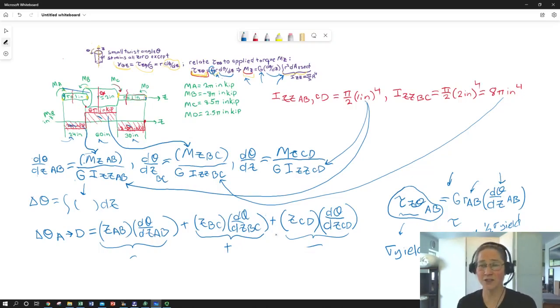I use the shear modulus to calculate all of my properties for a given applied torque or a given required twist rate or total twist angle, whatever, and the part dimensions. And then having calculated my shear stress, I make sure it's within the material capabilities and include any safety factors. So that's it for the setup of the problem. If you look through the Vable textbook, you'll see Dr. Vable goes through several pages and calculates this, pretty much sets it up the same way, give or take.